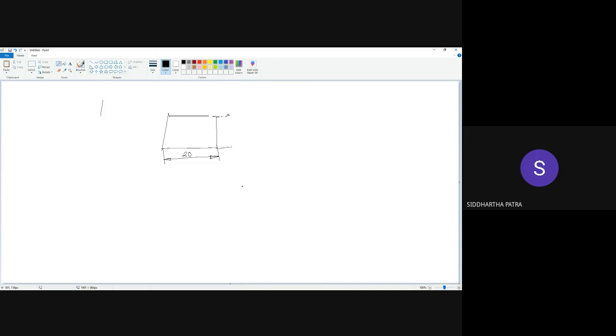And for a vertical dimension, I would go about it like this. Of course, the arrowhead should be completely dark, and there is a certain ratio that I mentioned for the arrowhead. So if this is your arrowhead, if this is 1, then this is 3. So if this is 1 millimeter, this length should be 3 millimeter. It should be that narrow, and it should be completely dark.